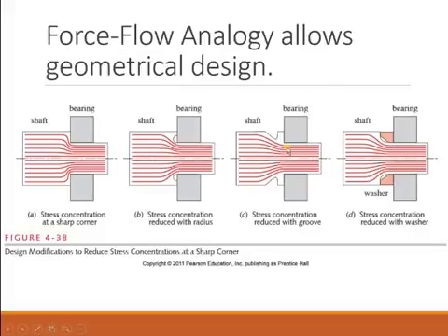But the more we think about it, it does make sense. The maximum stress is occurring here. If you think about it, all the forces have to be translated into the part right there at that corner very quickly, going from here to here. Whereas in this one, the forces are gradually allowed to transfer. So this one has a lower stress at this location and at this location, and then a huge jump in stress right there. Whereas in this one the stresses are building, so it has a higher stress in this region, but the change in stress as we move across the part is not as significant. And that's what we want to try to design towards.